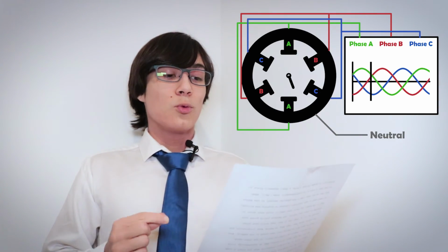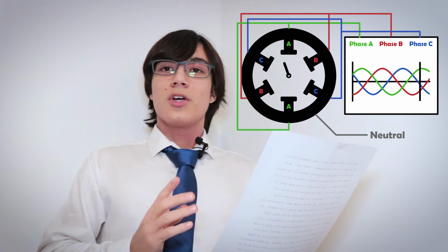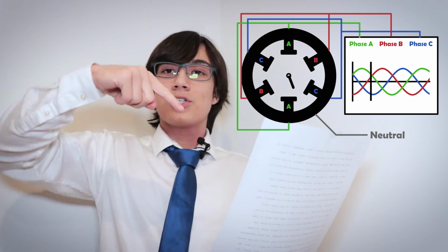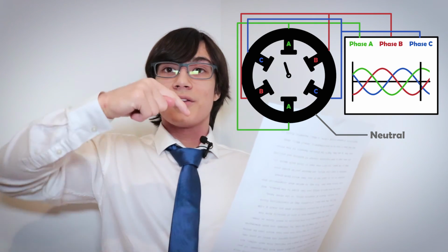But how does it work at an electromagnetic level? Well, when electricity is passed through a wire, it creates a magnetic field right next to it. You can increase this effect by making a coil of wire, and boom, you've got an even stronger magnetic field. These magnetic fields are created in a field around the wire, and because of AC current being in 3 phases, polyphase, the magnetic field will rotate around the center of the motor, so the magnetic field's direction will constantly be turning, rotating in a constant way.